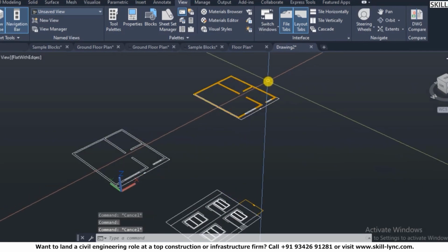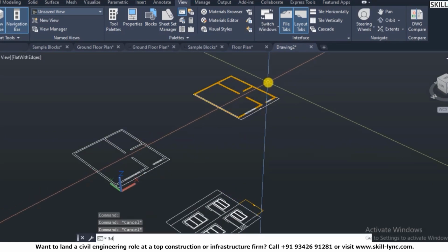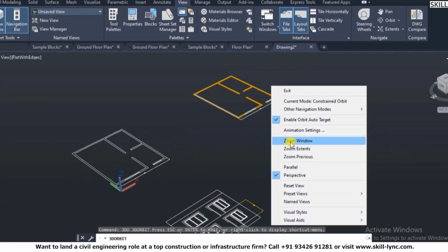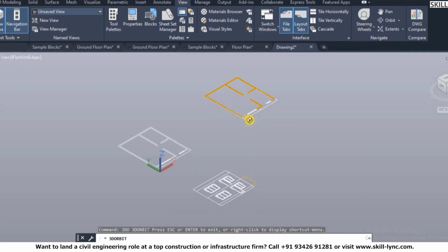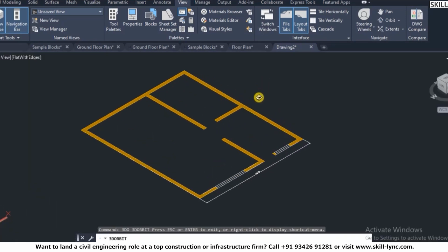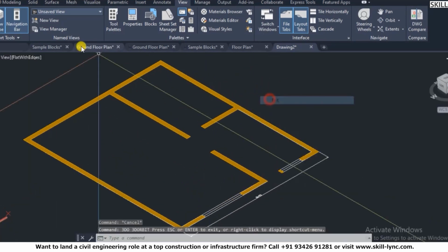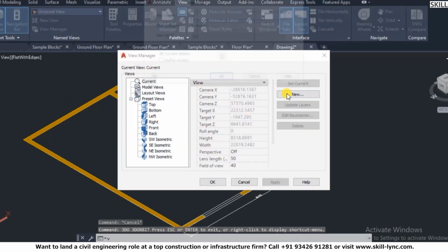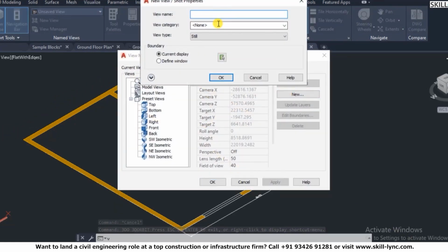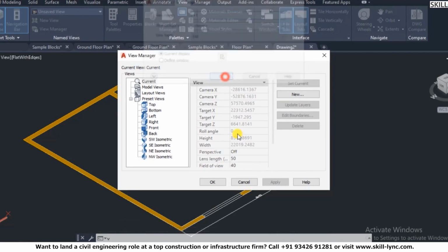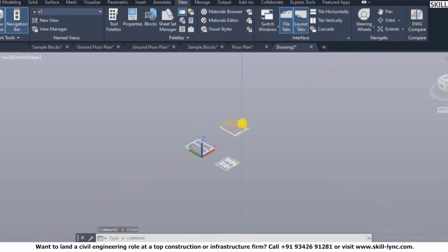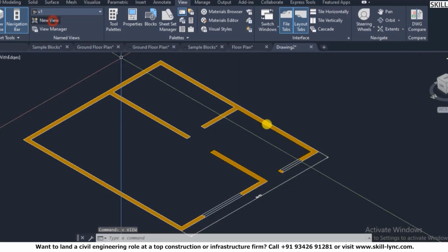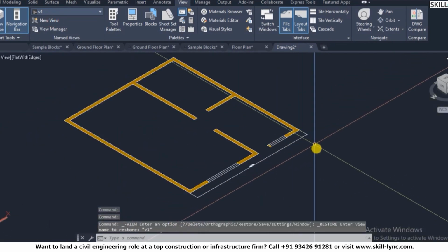So let's say now I will extrude. This is the region that I have right now. So I go to the 3D orbit and then I go for parallel projection. Rather than changing the view every time, I go to the view tab and set this view as, let's say, view 1. So every time I'm going to switch, I can always put the view on and come back.